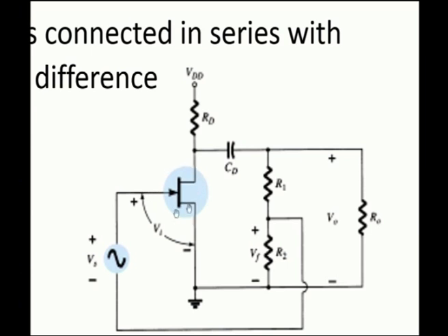And next we are going to see some of the practical feedback circuits. This is for the voltage series feedback. This is a field effect transistor, and there are two potential dividers R1 and R2 at its output terminal, and the voltage across the resistance R2 is taken as part of the output signal and given in series with the input voltage source.